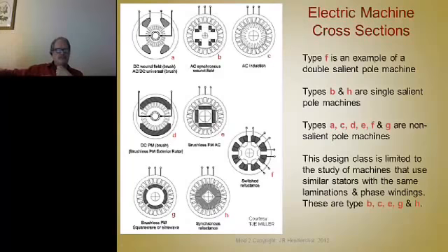But these DC motors evolved into synchronous motors. Remember, that was our second motor. It was an AC synchronous motor. It has a wound field on the rotor, much like the wound field on the stator of a DC machine. So this rotor produces DC current flows in these coils, producing north-south poles, and then the flux from those electromagnet poles in the rotor link with the conductors in the stator, so you have a synchronous motor.